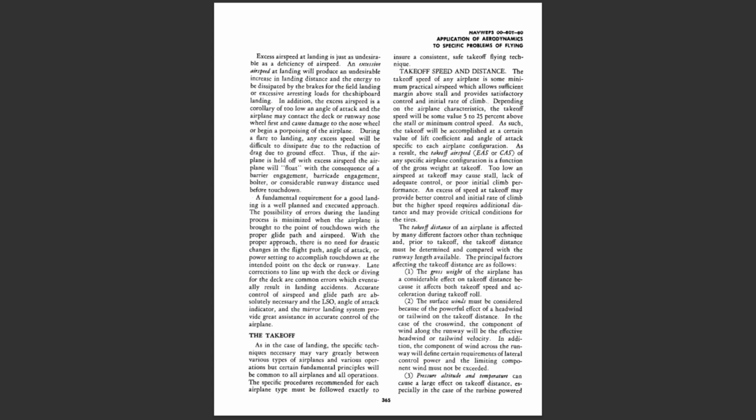Late corrections to line up with the deck, or diving for the deck, are common errors which eventually result in landing accidents. Accurate control of airspeed and glide path are absolutely necessary, and the LSO, angle of attack indicator, and the mirror landing system provide great assistance in accurate control of the airplane.